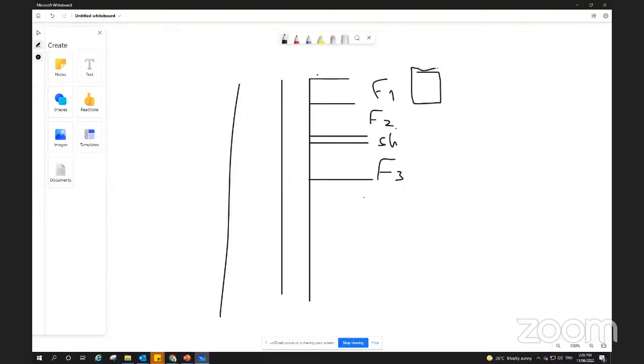Because I need a cell that represents these facies in reality. Then I want another cell that captures facies 2, and also another one that will be smaller, maybe smaller than these 2 cells, to capture the shale layer, because it's very important. Shale represents a flow barrier in simulation, so it's very important to be captured. And also another one to capture facies 3.